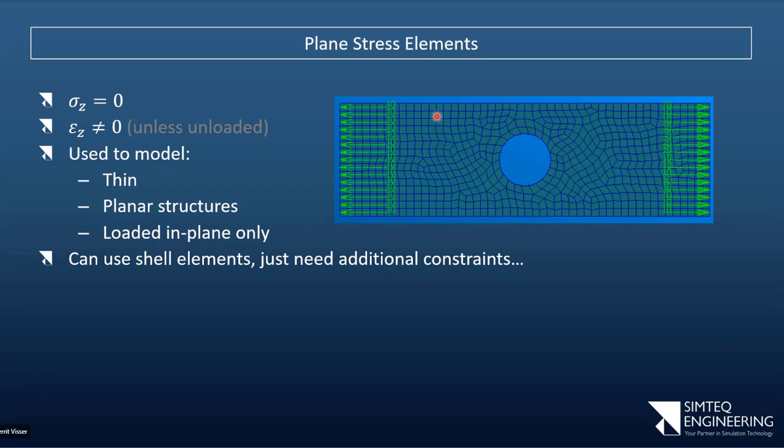If you look at the design of an aircraft wing, for example, it usually has a very thin skin, especially the thin metal skin ones, which means that they're guaranteed to buckle for certain types of loads. If you look at the pressure at the bottom of the wing that bends it upwards, at the top, the moment that skin goes into compression it is going to buckle.